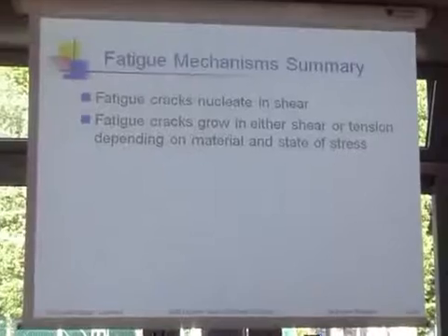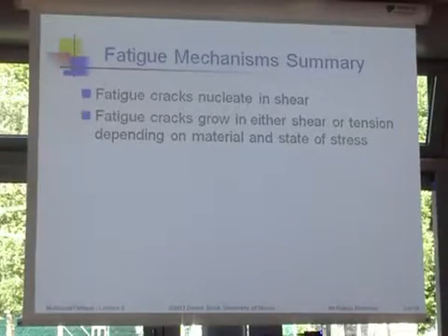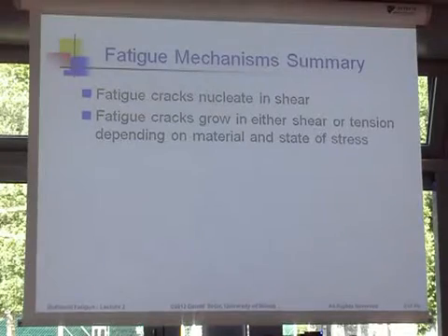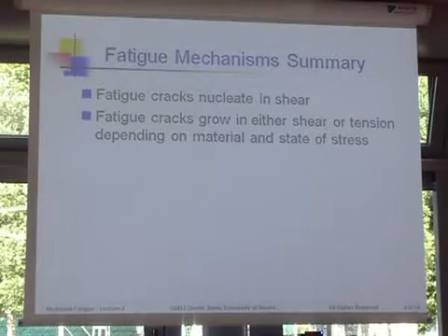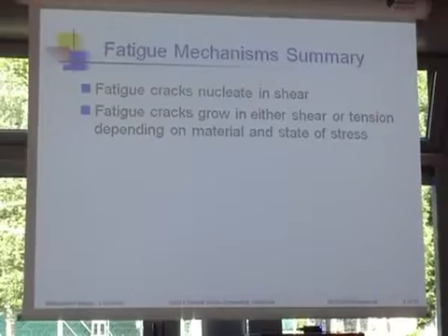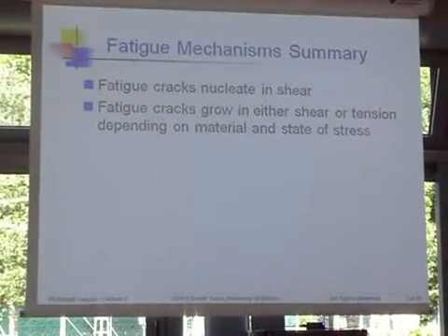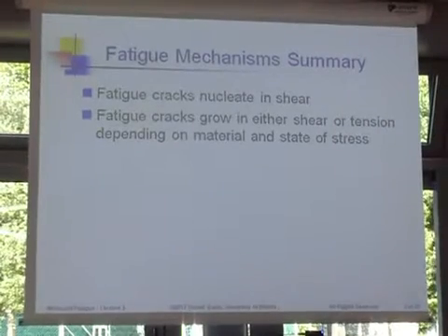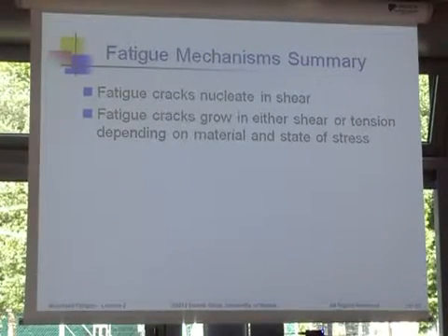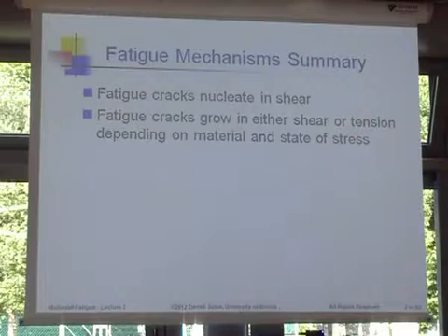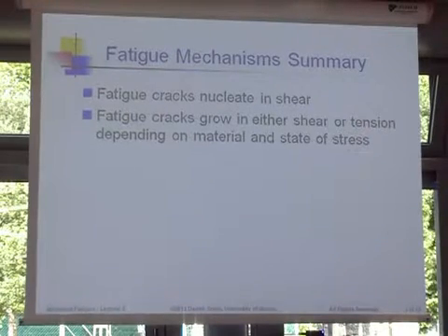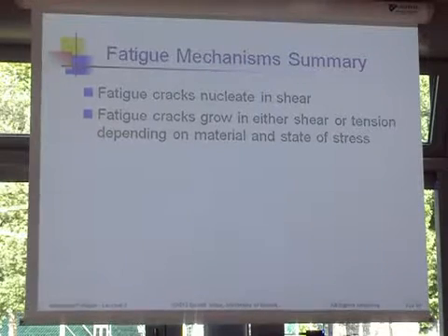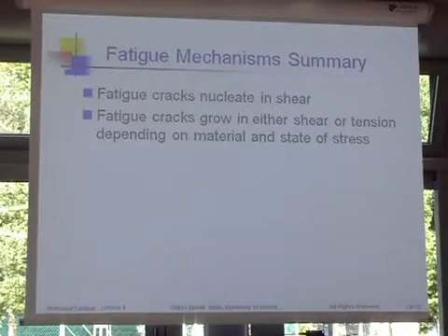If I just summarize what I spent the last hour talking about, fatigue cracks do nucleate in shear, no matter what mechanisms we look at in detail. Macroscopically they nucleate in shear because that's what's required for plastic deformation. Then after they nucleate, they have a choice to grow either in shear or in tension. Eventually they'll always be in tension at the very end, but that might be the last few cycles of life, for which we are not too interested.